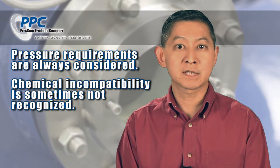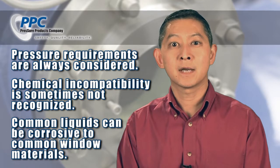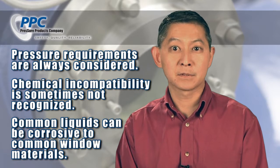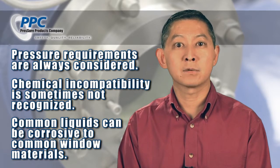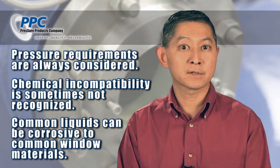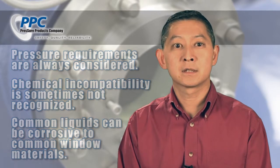A secondary issue is that some of the most corrosive liquids are common household materials that don't seem to hurt anything. And finally, reactivity varies enormously with temperature. So, in this segment, I'll go through some of the chemistry topics that you will have to think through before specifying a side window. Now, the vast majority of pressure-bearing side windows use silicate glasses as the transparent medium, so I'm going to discuss the silicate glasses. But you should remember that all of the issues we discuss here apply to plastic windows as well. Plastics are made through chemical manufacturing processes, and for any given transparent plastic, there is something that will attack it.